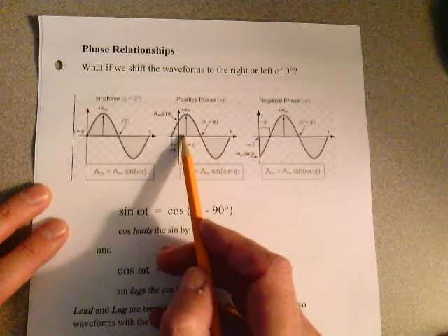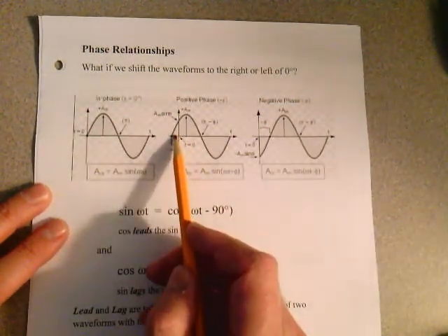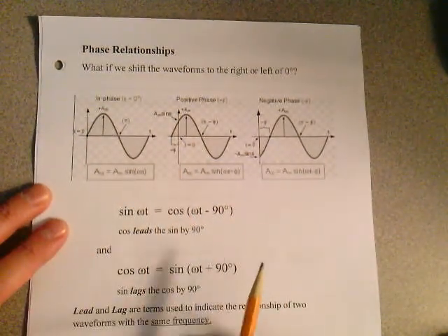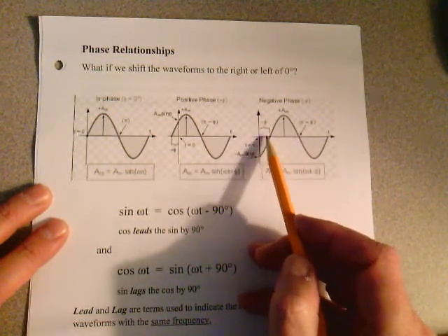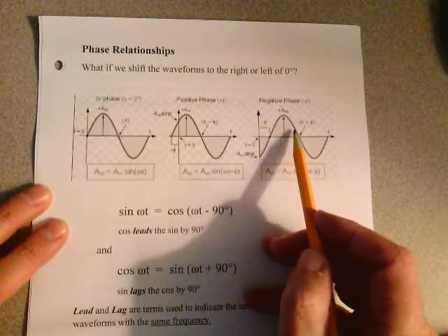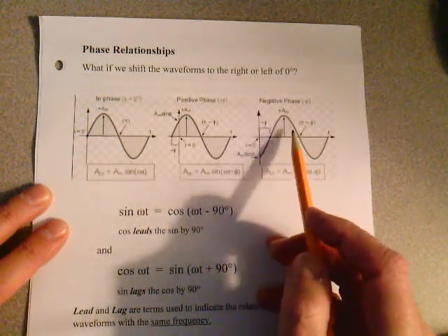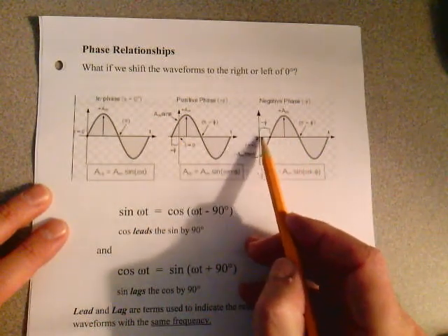If you shift that waveform to the left, you see that little angle right there? Whatever that angle is, it's a positive angle. If you shift that waveform, look what we did here. That sinusoid waveform was shifted from here to here. It was shifted back in this direction. That's called a negative phase shift. Now, I don't want you to look at it in terms of anything to the left is negative and anything to the right is positive.